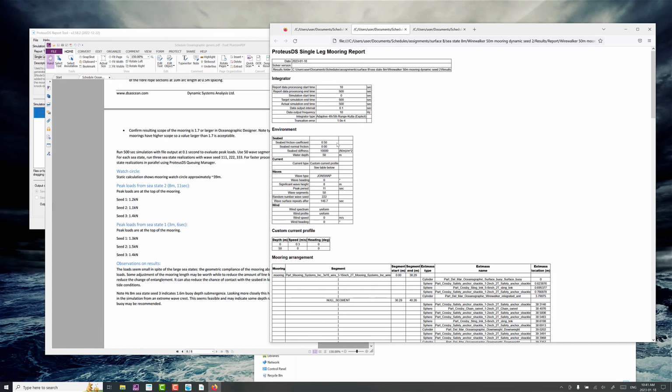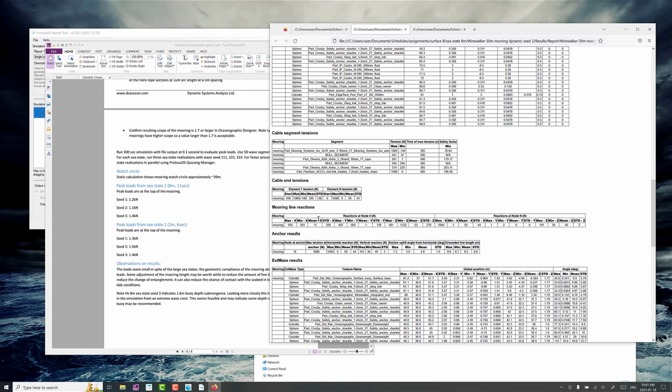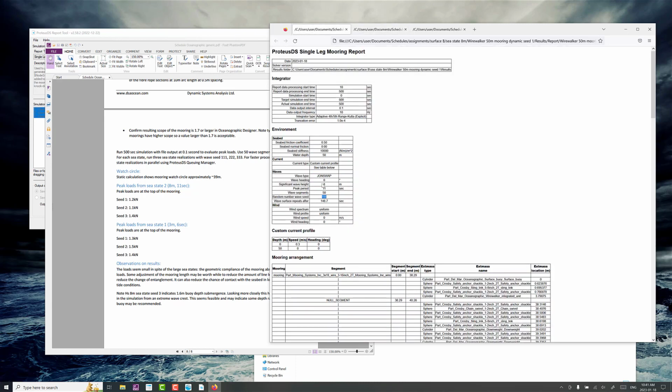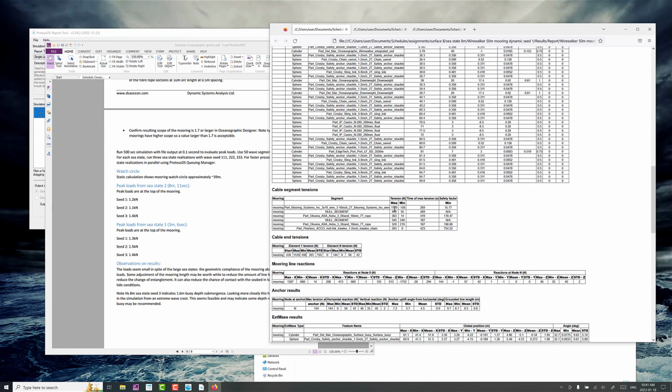So this is seed number 2 that we have, and we've got a maximum of 1.1 kilonewtons. That's expected. And then seed number 1 for the 8 meter 11-second result, we've got 1100 newtons. Oh, it's a smidge under that, 1.1 kilonewtons instead of 1.2 kilonewtons. That's pretty close though. All right, and then of course looking at safety factors for all these components, that's far above the breaking strength for many of these components.